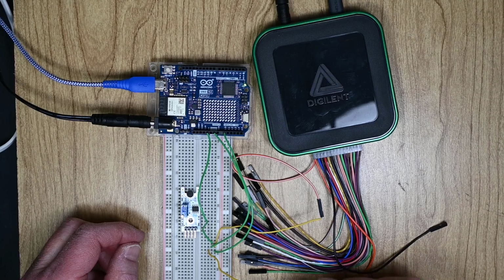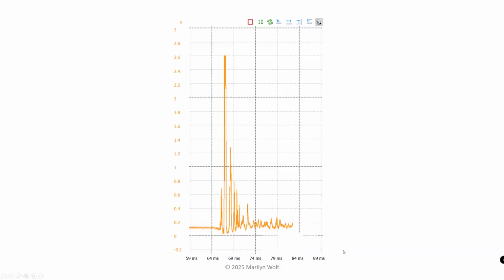We'll use the analog output. Here's a waveform for a clap. We can decimate the signal to reduce its sample rate, then use a histogram to describe the overall shape of the signal. We can compare the signal's histogram to a template histogram in order to see whether we've matched what